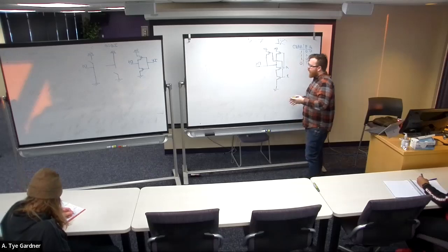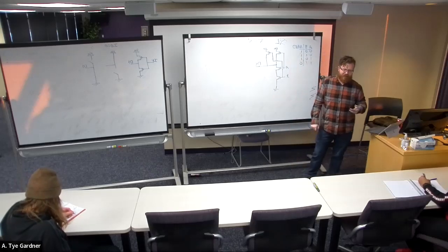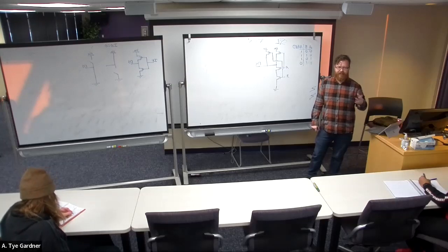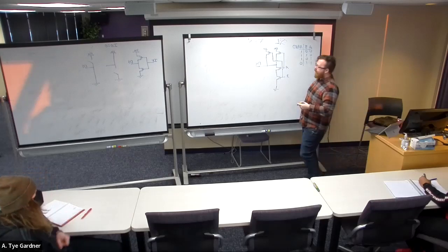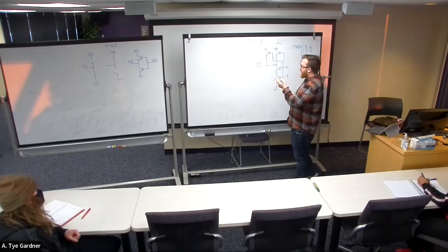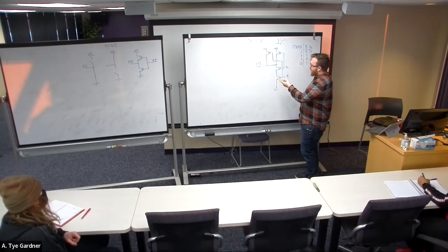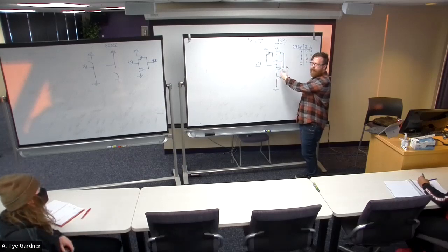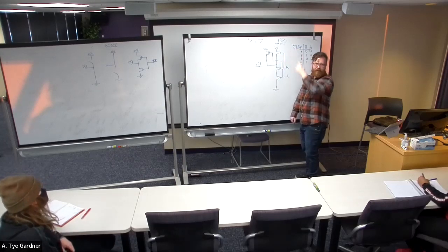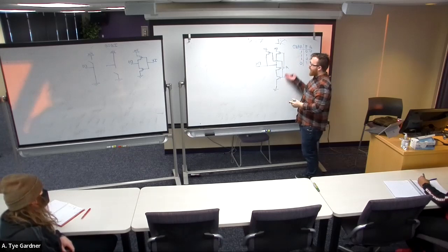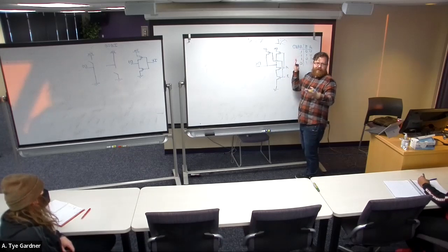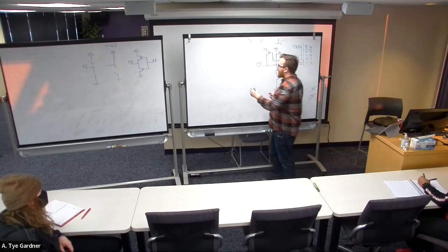And there's this kind of intuitive build to this, which is like OR is almost like the opposite of AND. Sometimes it feels like, right? It's just whatever an AND is doing, the OR is just counter to that. It's not quite true, but ORs have that feel to them. And so we can imagine, let's just build the opposite for the pull down and the opposite for the pull up, which is let's make a parallel pull down and the serial pull up and see what happens, right?